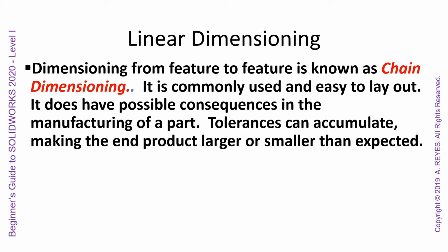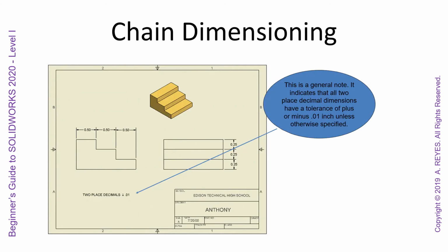So it may be used in some different types of drawings, outside of the manufacturing environment. But with the new geometric dimensioning and tolerancing standards, they've gotten away from linear dimensioning, and we'll look at datum dimensioning here in the next one. But I just want you guys to understand what linear dimensioning is.